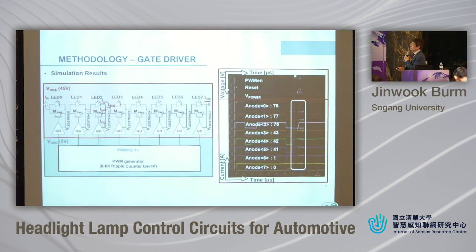So in the case of LED 0 to LED 4, the starting current will be maintained as a single amount, and it will come out as I out. In this process, all these switches turn on and off. For this simulation, we tried all these different conditions. The worst case is happening for LED 7. The worst case is when all the other LEDs are off, because that will introduce additional current paths to LED 7. So to test the working condition of LED 7, we try all these different conditions and make sure it's working okay.